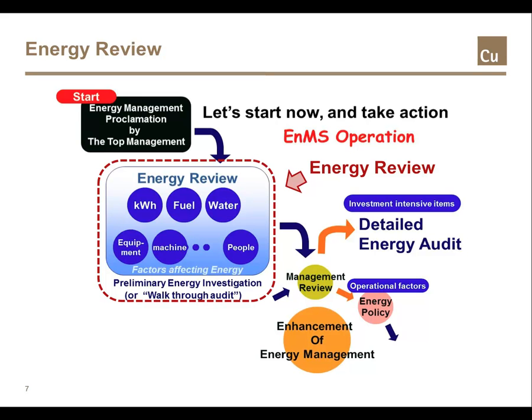For the energy review, various energy associated data need to be collected to understand the current energy status in the organisation and to identify significant energy use items, as well as defining an energy baseline and target, as well as energy performance indicators. The next step is to conduct a site walkthrough energy audit that's in line with the energy review objectives we just set out. In other words, they seek to identify energy conservation opportunities that require little or no capital expenditure, ECOs, and the technical aspects of the operations, and affordable and adaptable first phase energy monitoring and procedure improvements.